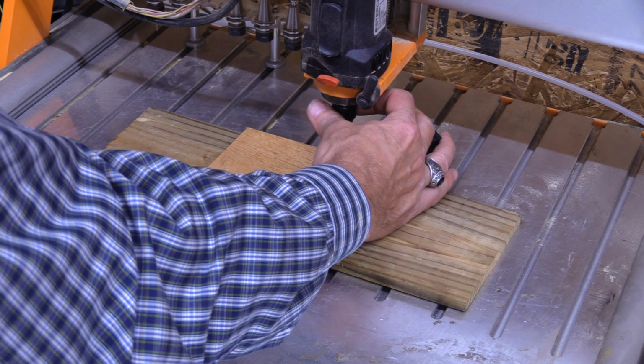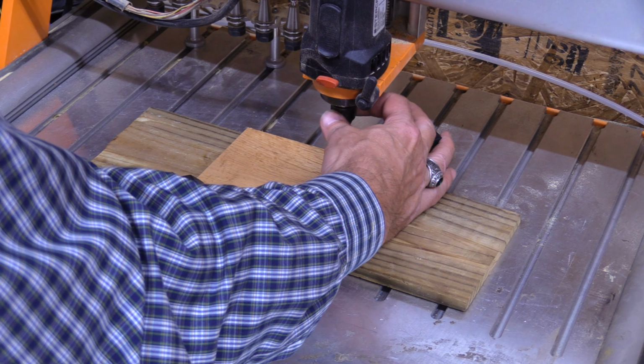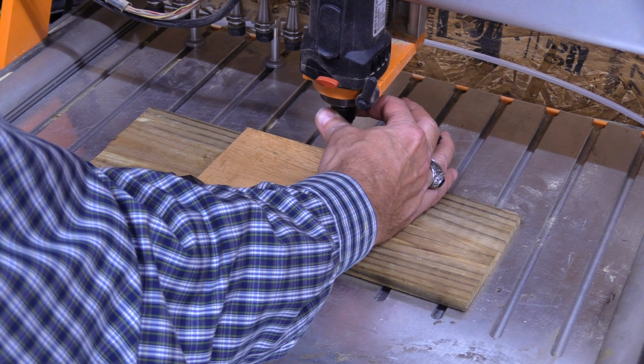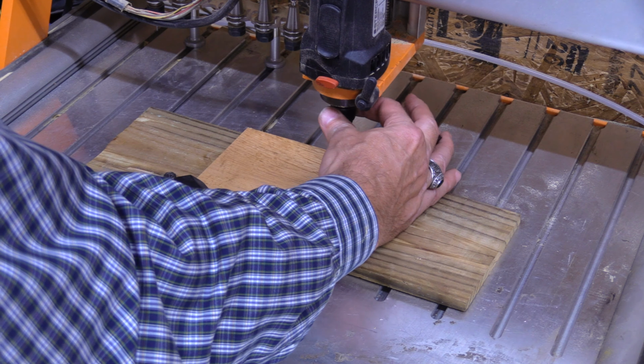So I can just spin this by hand. I'm not going to turn the motor on, and I'm going to slowly move this, just jog it a little at a time until I can feel I'm right against that piece of wood, right? So I can feel it moves just a little bit, and I'm going to set my Y0 at that point. Bing. All right.